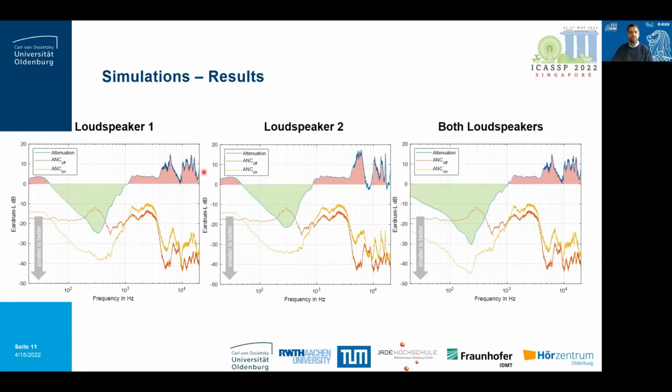If we concentrate only on the red areas, we see that for all ANC controllers an amplification is produced, whereas this amplification remains below the maximum amplification of 4 dB specified by G2 up to 4 kHz. It exceeds this value for higher frequencies. This may be due to the fact that the assumption that D and R are equal does not hold in this frequency region, because the wavelengths are comparable to the distance between the inner microphone and the eardrum. However, it should be noted that this happens in a frequency region where the passive attenuation of the in-ear headphone is very high.